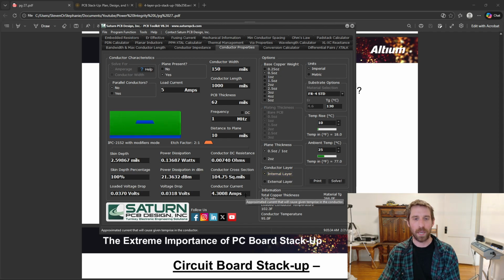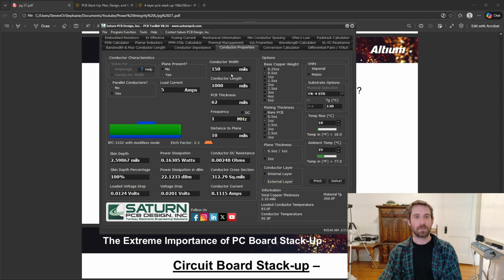Well, okay, you might say, you've got a huge plane and whatnot, so you can do significant. So yeah, that's fine. But point being, I can do it on an external layer. And because of the thicker copper, and because this heat can radiate into the air, I can get more current out of this. So it's not as big of a deal.